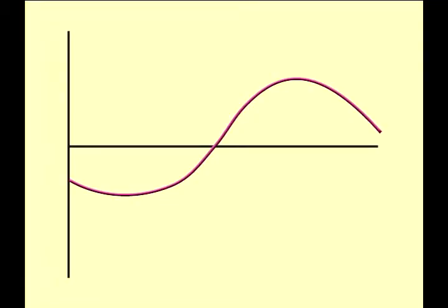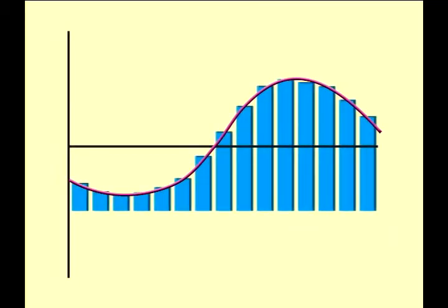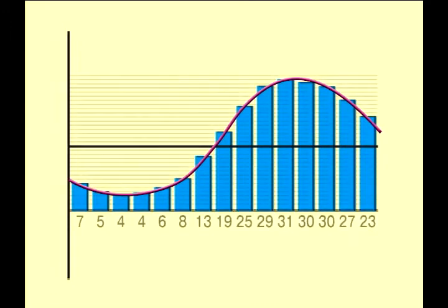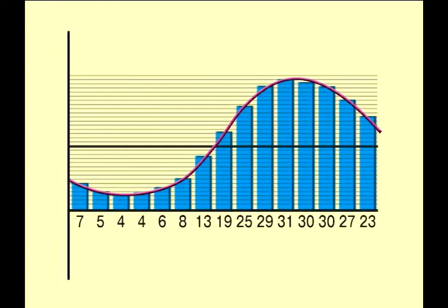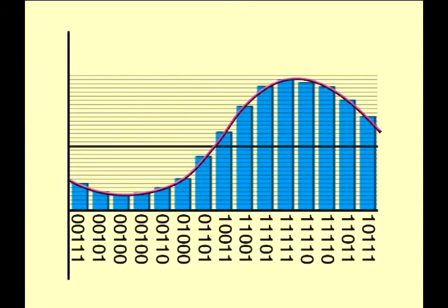This graph shows an analog signal drawn using fixed-time pulse width, a process known as sampling. Next, the heights of the sampled data are replaced with numerical values. When expressed as binary numbers, the numerical values look like this. In this way, data for temperature and pressure are converted into digital data and used in measuring devices and computers.